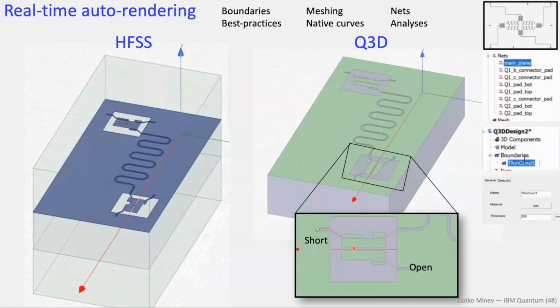And you have quite a bit of flexibility, because what you're doing now is you don't want to analyze the entire chip at once, because that's just way too much at once. So usually you simulate parts of the quantum chip. And to do that, you have to be careful about how you break up the quantum chip. So we've been very careful, and Dennis did a lot of work here on when you break up the model and render it into an analysis, whether things are open or short or something else, you can really tailor very carefully and neatly each of these properties here.